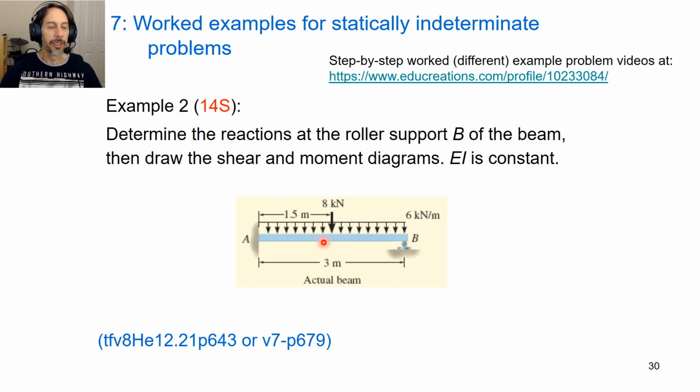The other thing you can do is to draw the free body diagram, put in your unknowns, and then count up the unknowns. That of course assumes that you've drawn your free body diagram correctly. I've seen a lot of assignments and exam solutions from students where they've got the free body diagram wrong. They've drawn a free body diagram that's not statically indeterminate, and then gone on to use indeterminacy procedures to try and solve the problem, which is total nonsense. So it's critical you get your free body diagrams right. Anyway, let's go through the problem.